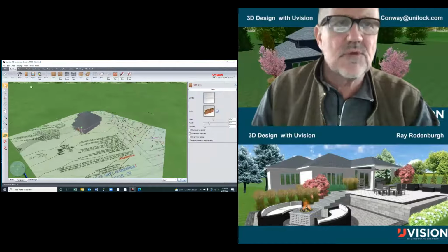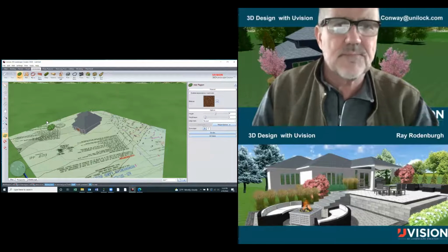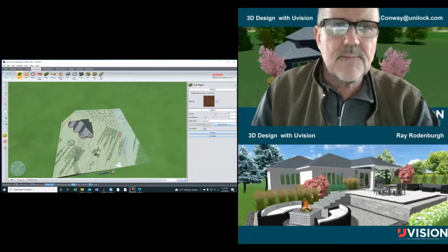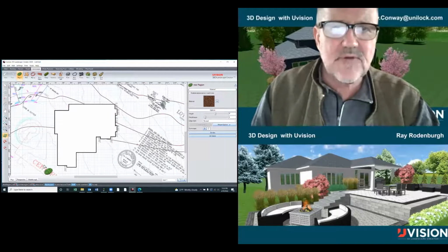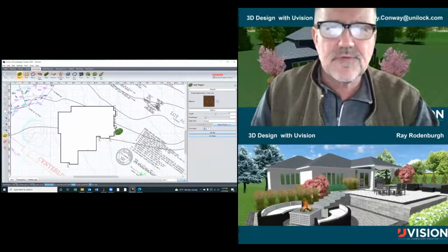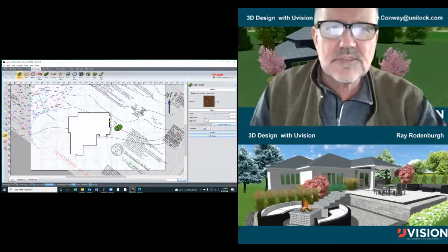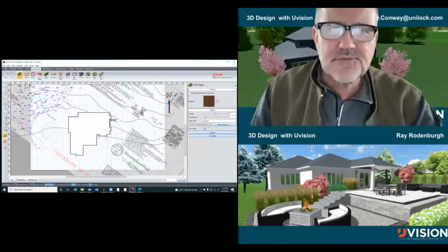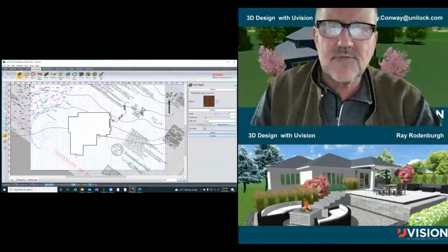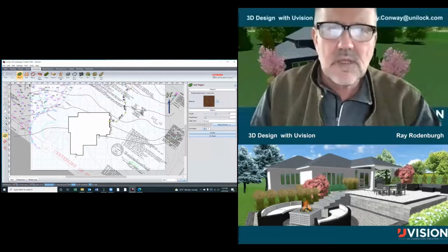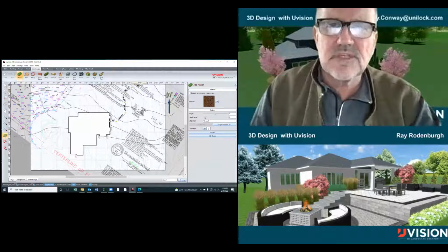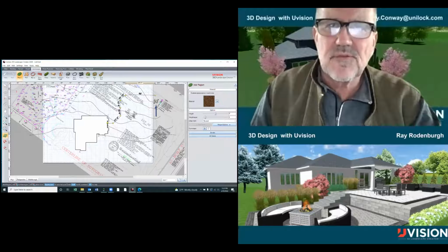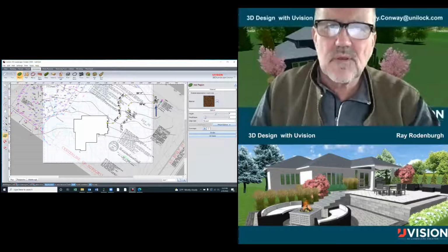But if you want to put a driveway on the surface of the existing land, what you do is you can go to the word landscape region, and I'll do it in plan. Let's see if I can find the door again. There's the door, I believe, right there. So I'm just going to do this. I'm in region. I'm going to straighten the lines because we've said it 100 times. I'm just going to stop it here. Let's just say the driveway stops there. I'm going to come back and straighten some points up here. Parking bay.